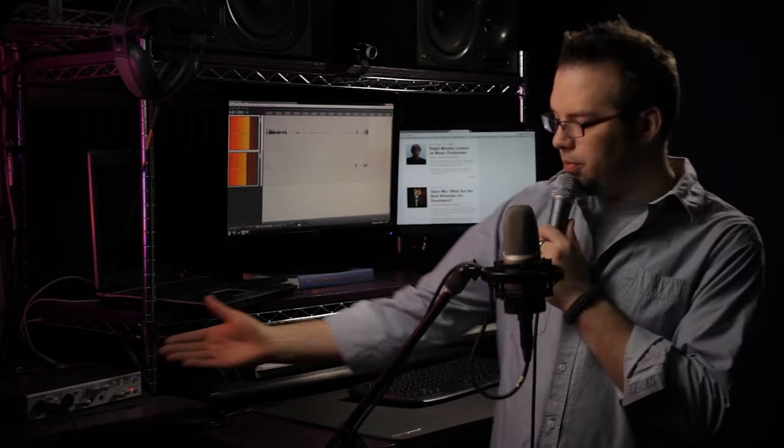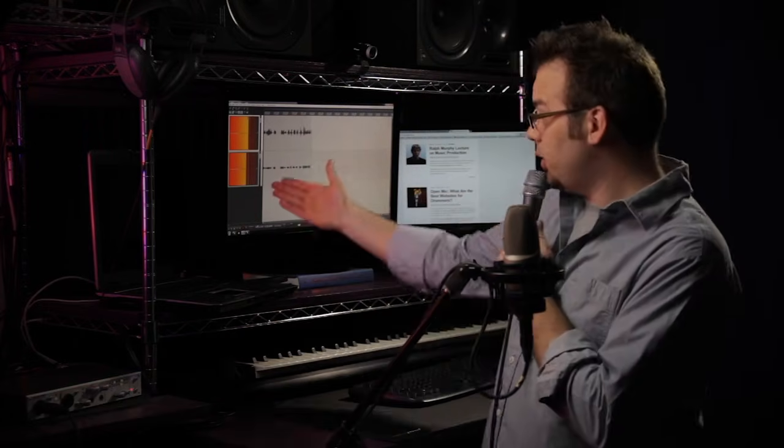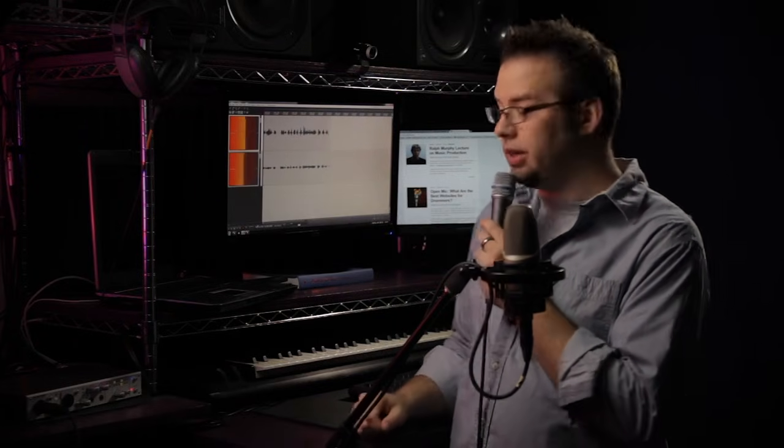So now let's check out this same microphone when plugged into an actual microphone preamp. Now I have plugged this microphone into the front panel, which is the same exact channel. And by doing so and switching this mic line input selector, now it's running through the microphone preamp. And you can see now that I have a much healthier signal to work with.